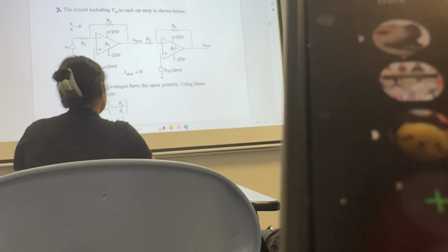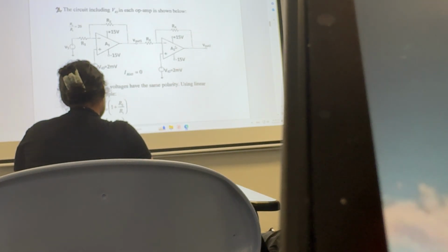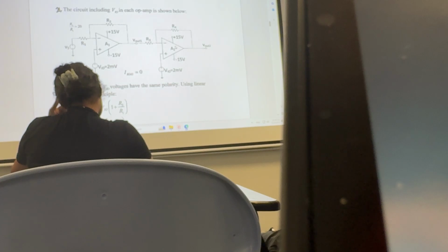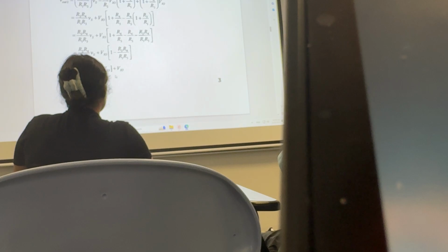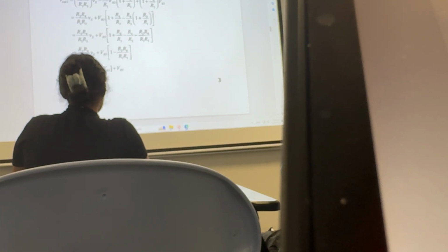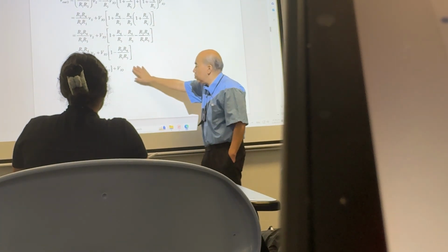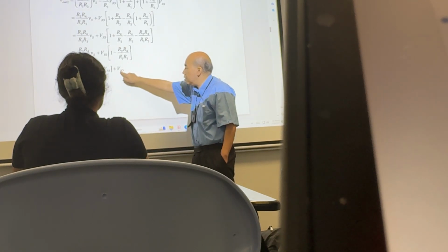So you can see that when they add together, this one and this one cancel. At the end you get plus offset. Part of the offset component from here will be cancelled with part of the offset component from here. At the end you are left with V offset. So this is the formula. Intuitively you are able to interpret the design. There is some partial cancellation for the other terms, so you can definitely write it out here.